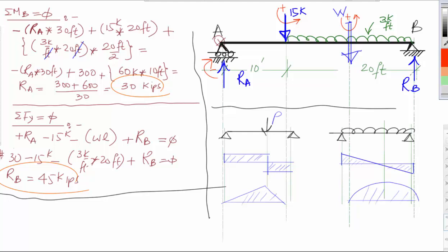Having these in mind, you should always have some sort of estimate of what the bending and shear diagram for this one will look like, because what we'll do in the calculation is just get the exact locations. If I would do some sort of guessing based on these, shear will go like that and come down, and then go like that.